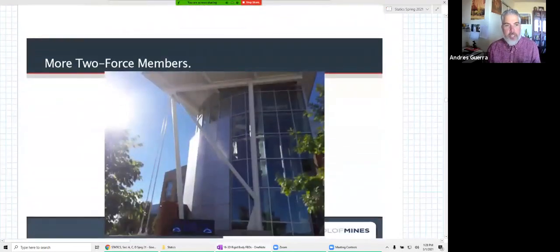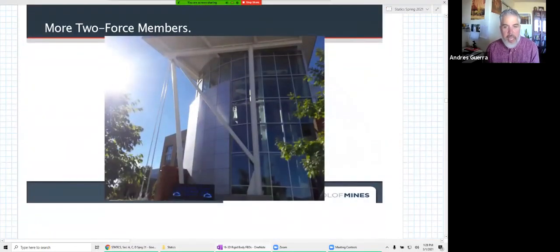How about these ones, though, on the rec center? If it only has two locations of forces, it is still going to be a two-force member. So, for example, this one right here only has two locations of forces. One thing we're not sure about is whether or not these resist a moment, because remember, if there's a moment applied or a moment from a fixed support, then it's no longer a two-force member.